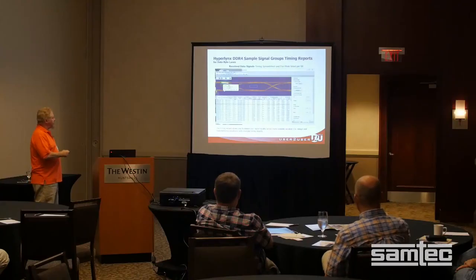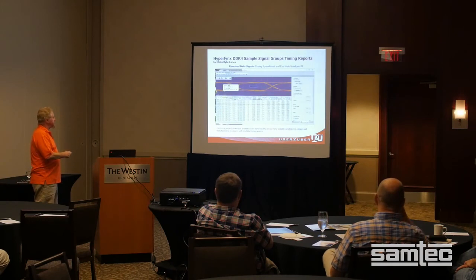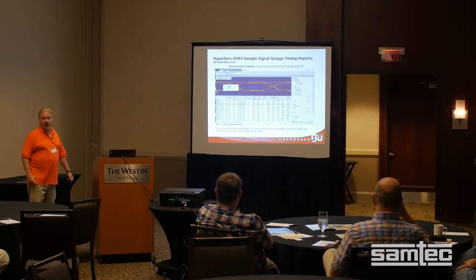Now, I hope that every one of you would click on every one of those and look at every waveform. Or do you say, well, look, it says pass on everything, we're done, ta-da? No, click on every one of them and go down it. You don't have to do anything else. You click here, it brings up that simulation. Go through every single one.